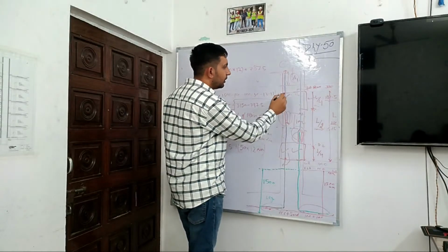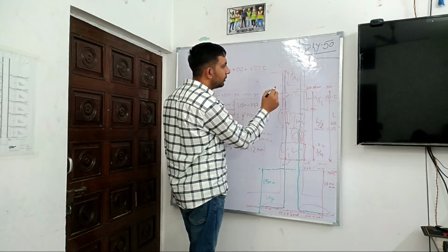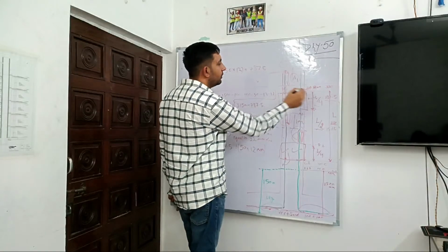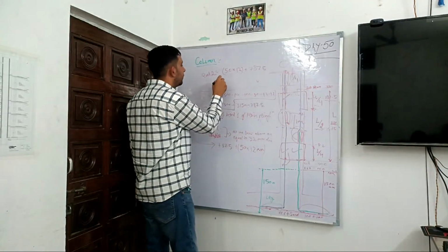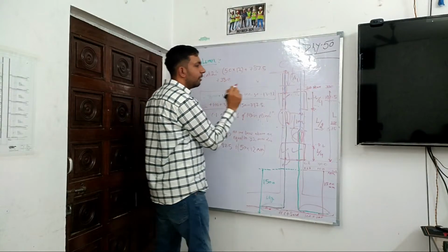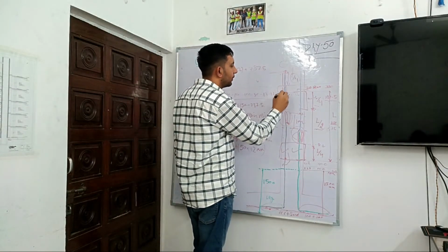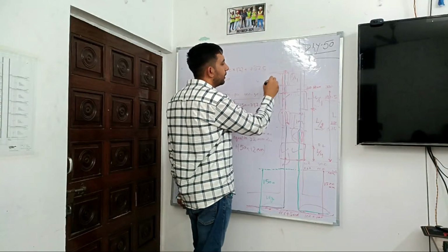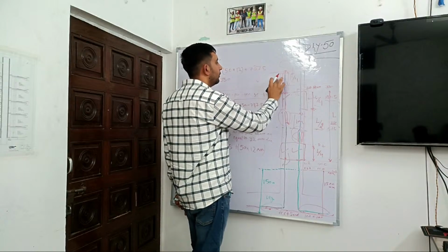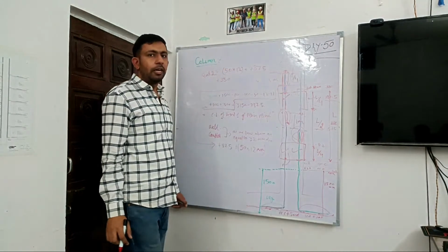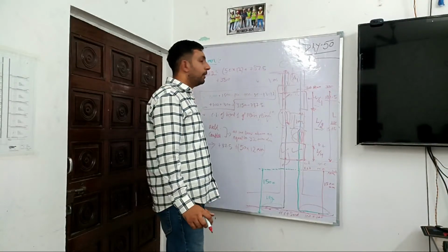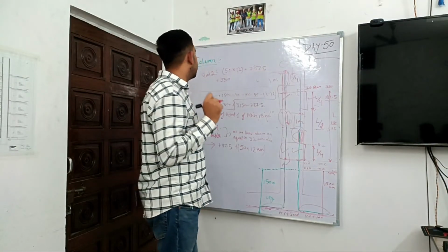So we have reached here, but we have to reach here. Then add 350 also, because it is the depth of the slab beam. Above the ground floor's roof slab, we have a parapet wall of 1 meter. It means we have to end our rod at the parapet wall column, while subtracting its cover.